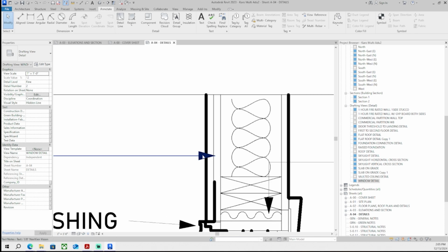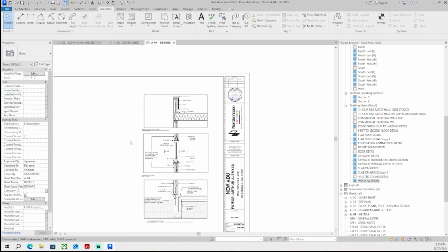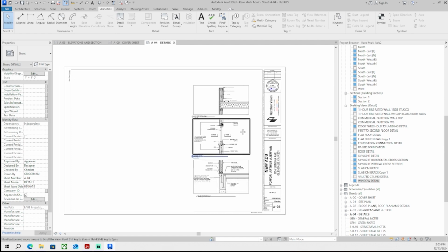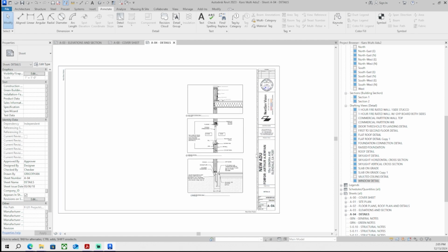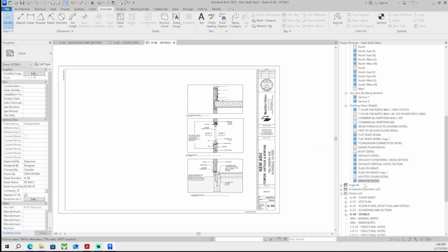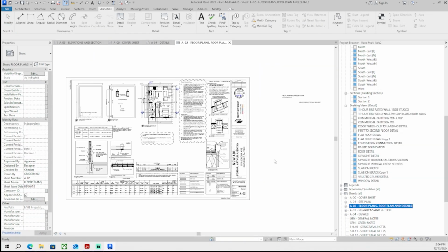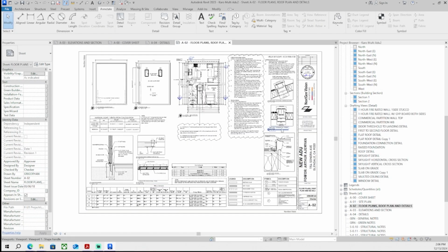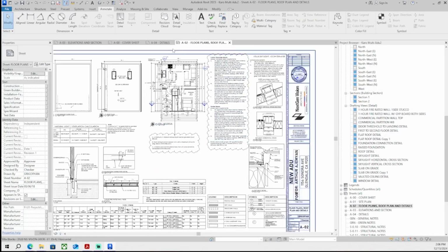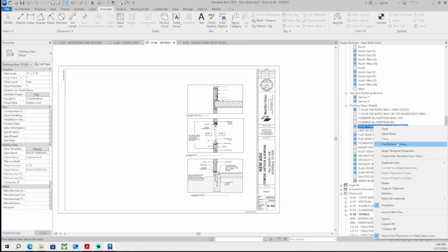You don't want it causing your metals, your rebar to corrode. You don't want water being poured into your foundation wall or poured into the interior space. That's why we have the threshold at the door, and that's why we have the sloping away from the foundation wall on the exterior.